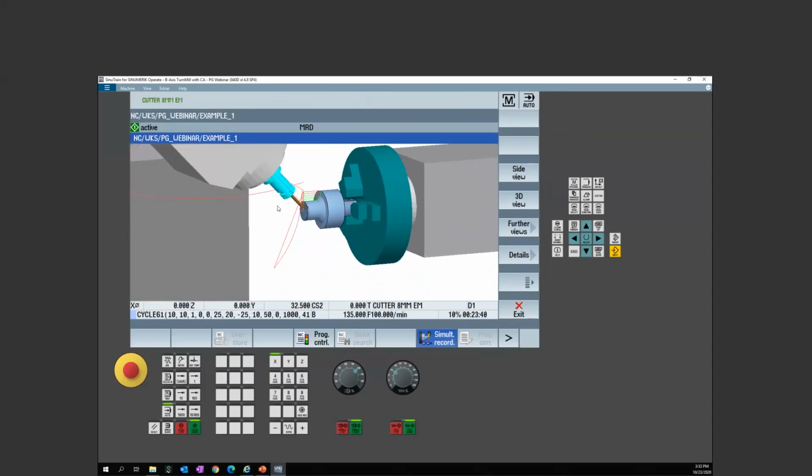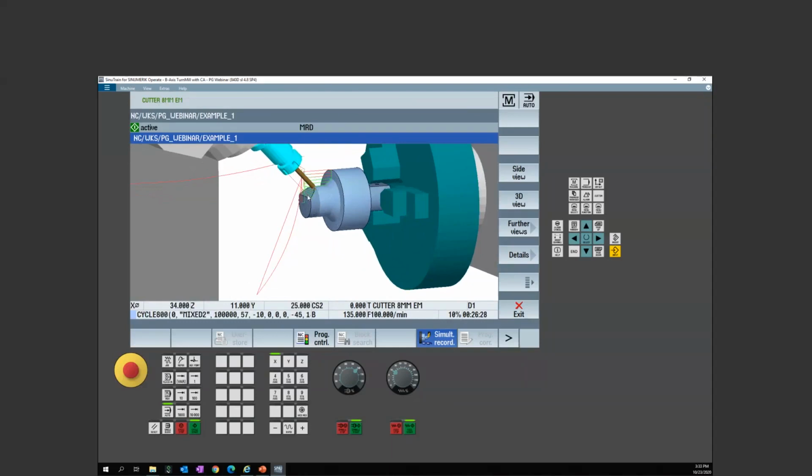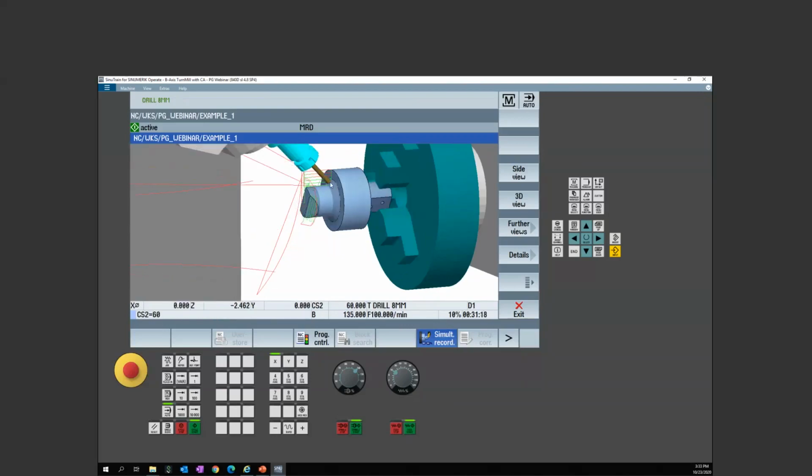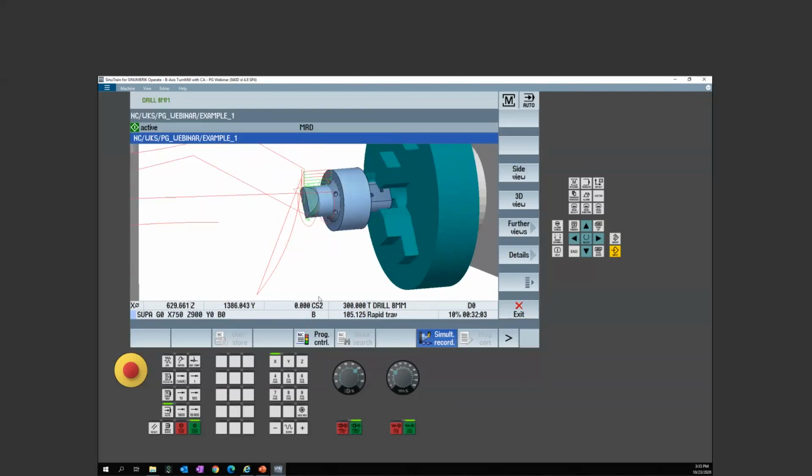Now we're at an inclined plane, machining the flat. My 0 is staged right here at this corner is where my new temporary 0 is, while cycle 800 is active. Certainly if I cancel cycle 800, it goes back to my global 0. Then I'm going to position a 0 right there. Boom, boom, boom. Drill my holes. And away we go.